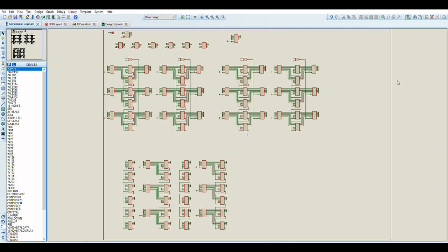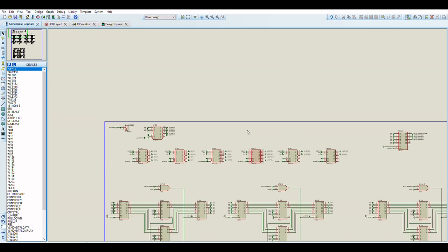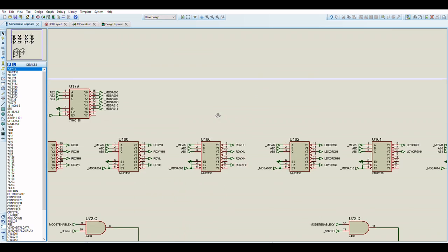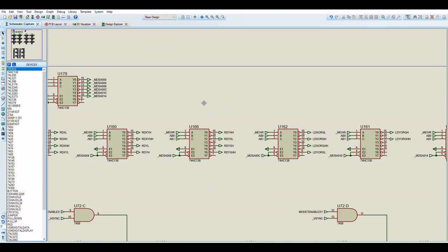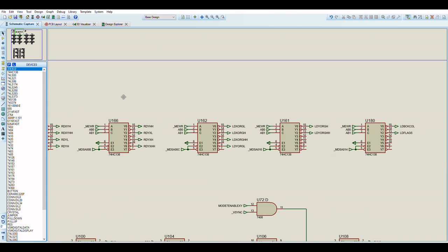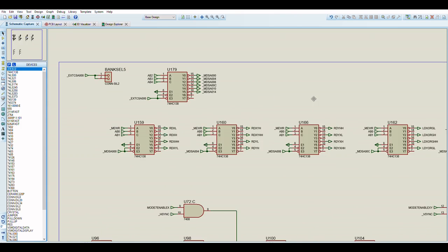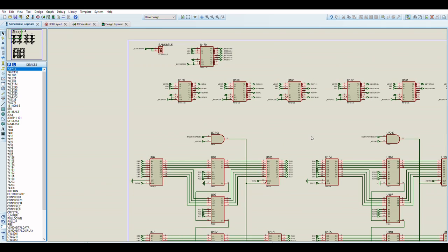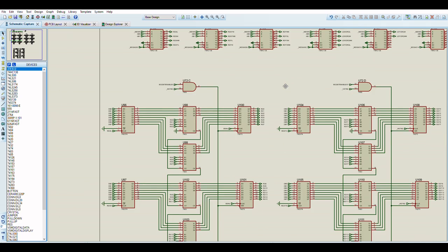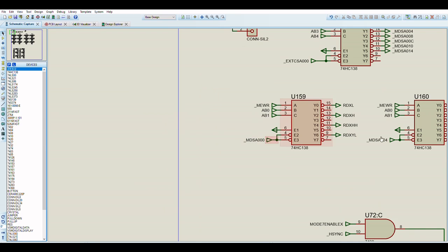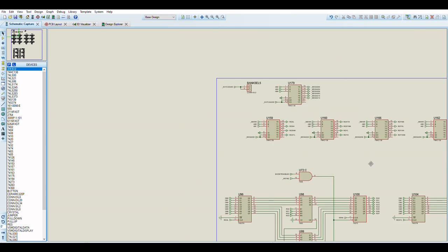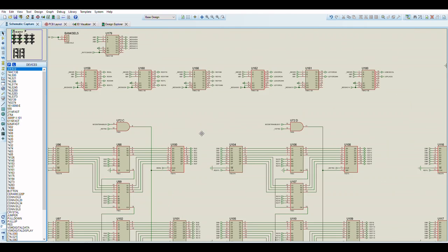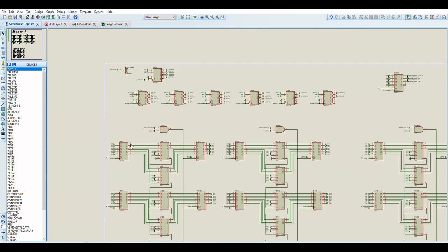This has register addressing. So this calculates which register 8-bit latch to enable based on the memory that I'm addressing. In terms of memory space, this is A00 onwards in hex. And these latches here then latch the information here.